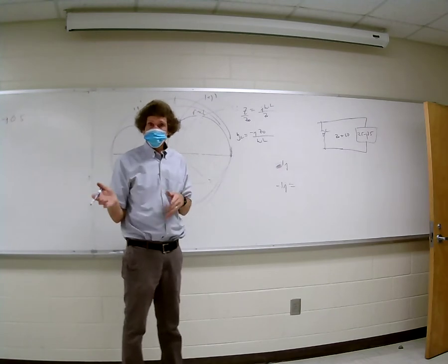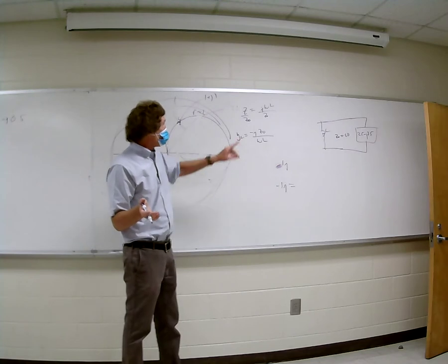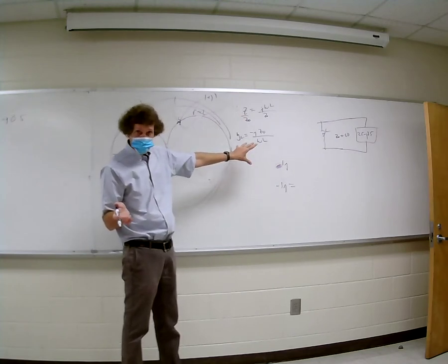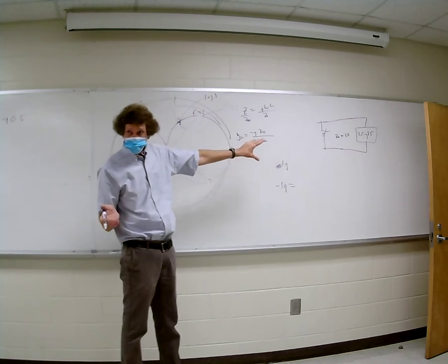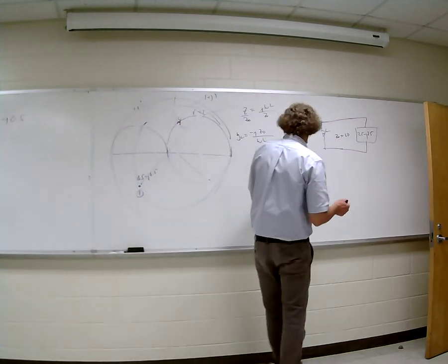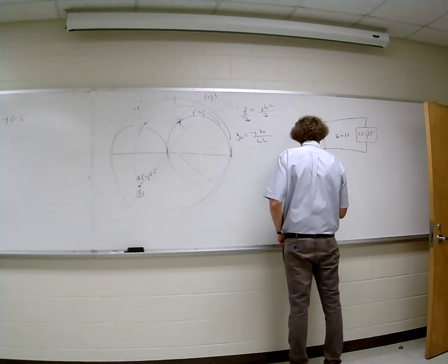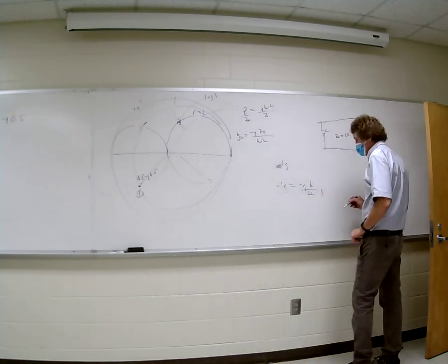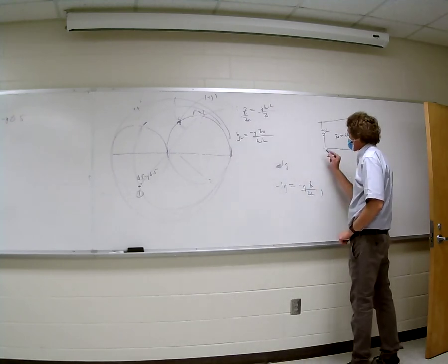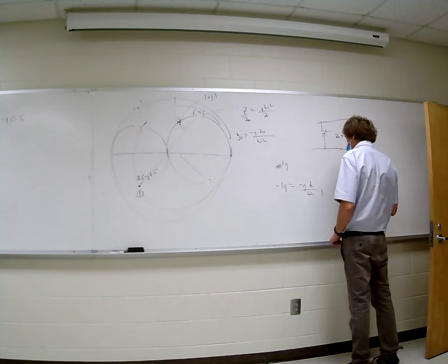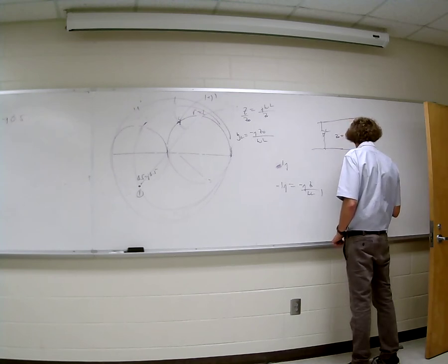Just think about what I'm doing. I took 1 over the normalized impedance to get the normalized admittance of an inductor. It's got a minus J, right? Y'all with me? I have to set that equal to this. So I have minus J Z naught over omega L here. And that means when I calculate the value, this is one element that's going to match. That would be in parallel for L. It would be L is simply equal to Z naught over omega.